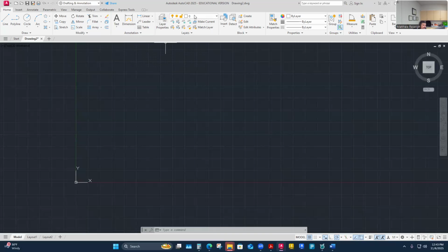I'll already have built some layers. You have nothing right now. Default CAD just gives you a 0 layer, and if you drop this down, it's only one layer. When I send you my actual drawing, I will have built out a bunch of layers. All layers are, really, is where I store my different line types, is mostly how I think of it. Instead of everything looking like the same type of line, in CAD we kind of color code it.